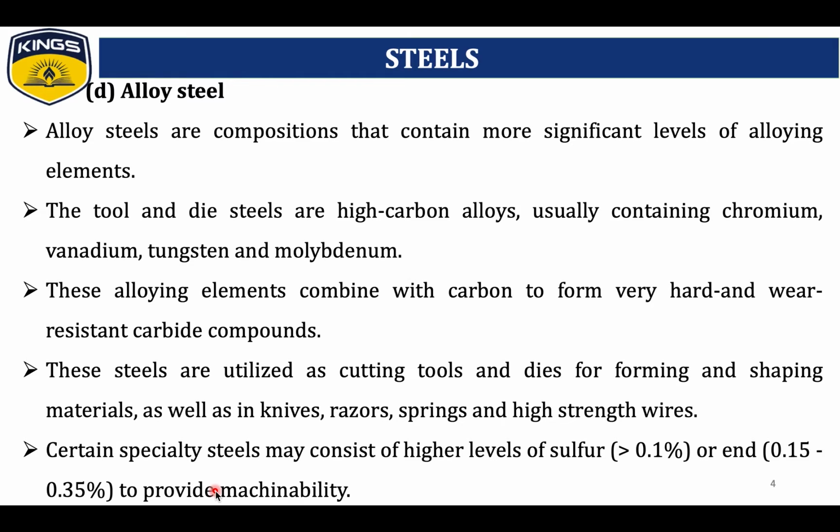Some specialty steels may consist of higher levels of sulfur, that is greater than 0.1 percentage, or 0.15 to 0.35 percentage, to provide machinability.